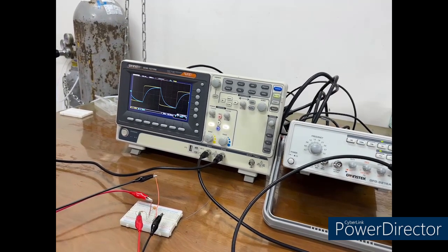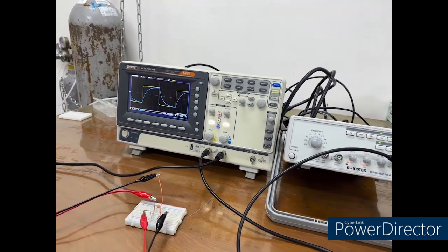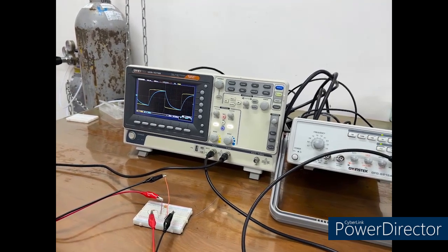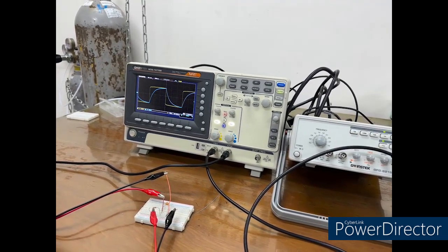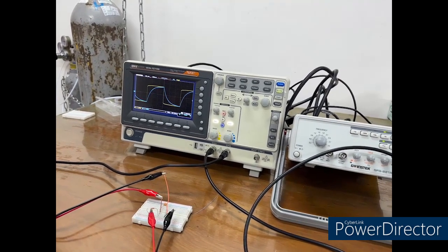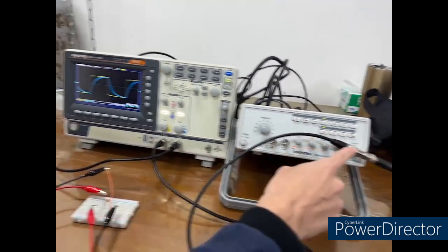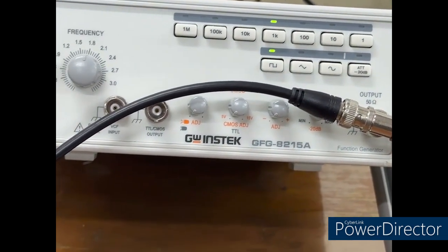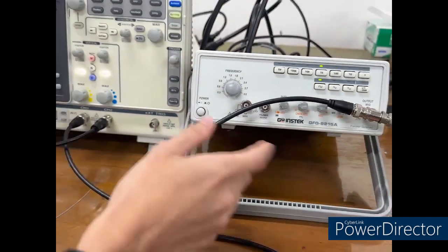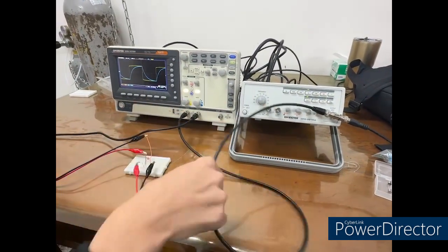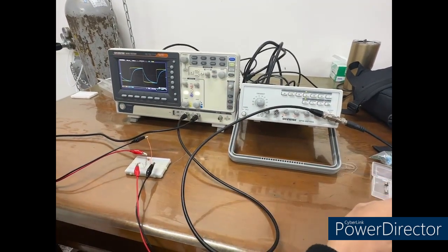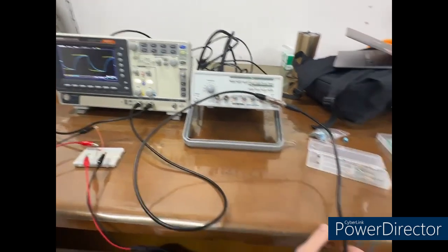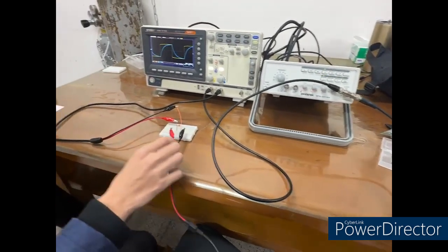In this experiment, we are going to observe how an RC circuit works, including discharging and charging on a capacitor, and understand some methods to measure the capacitance value. Let's look at how we connect the circuit. First, we use the T connector on the function generator. The T connector splits the output to channel 1 of the oscilloscope, which we measure, and the other goes to the circuit charging our capacitance.